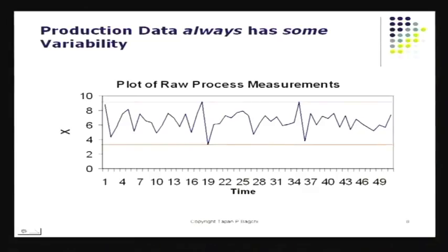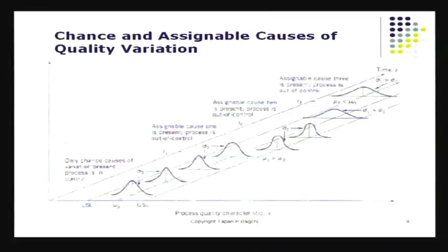I cannot really control these two aspects of quality, which are accuracy and precision, just by using the raw chart. It's not possible. I have to convert this raw data into something else, and I'll show you exactly what I do. In fact, this is the heart of statistical process control. Now look at a process.